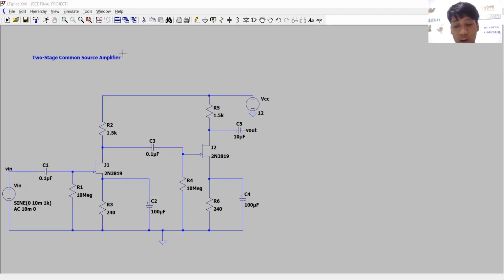One of the main disadvantages of using the FET or the field effect transistor is that they need to be negatively biased. If this bias failed, for any reason, the gate source voltage may rise and become positive, causing an increase in drain current resulting in failure of the drain voltage. Also, the high channel resistance coupled with the high quiescent, or steady-state, drain current makes this device run hot, so additionally a heat sink is required.